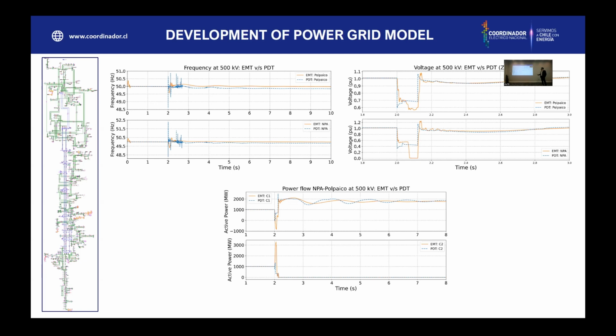There are big differences here because in EMTP, the way of modeling surge arresters is very different from what they do in Power Factory. And this is why we see different stages of the same fault, because at one point the varistor is discharging, and then it's short-circuited because it's maxed out.